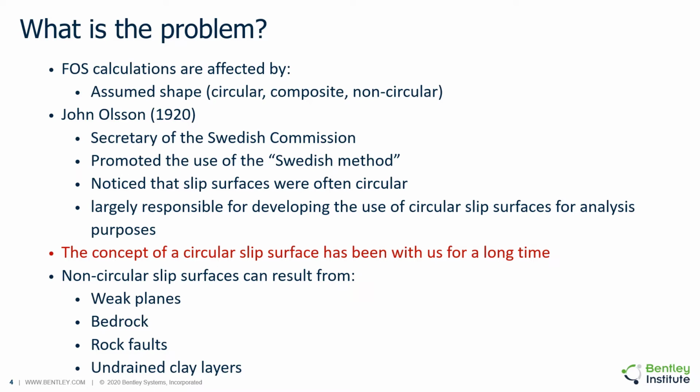It has been found that a number of scenarios can also yield slip surfaces which are non-circular. Weak planes, bedrock, rock faults, or undrained clay layers can all yield conditions which result in non-circular slip surfaces. Therefore, the software must be comprehensive in considering both circular and non-circular trial surfaces.